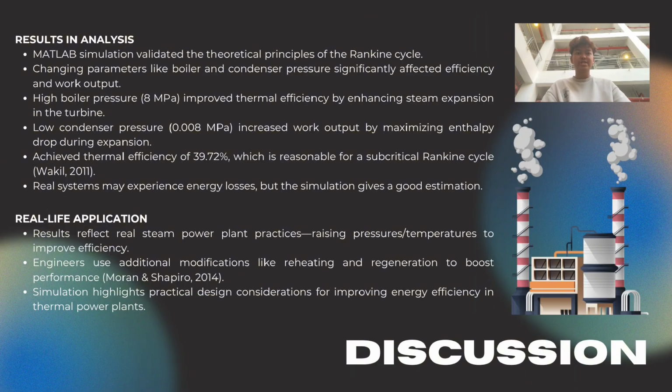Next, we move on to the discussion part. The results from our MATLAB simulation successfully validated the theoretical principle of the Rankine cycle. So we observed that changing the boiler and condenser pressure had a significant effect on both efficiency and work output. For example, using a high boiler pressure of 8 MPa improved the thermal efficiency by allowing the steam to expand more effectively in the turbine.